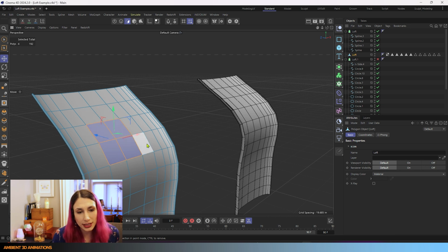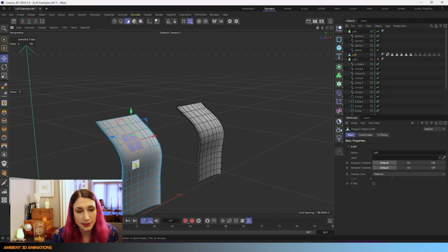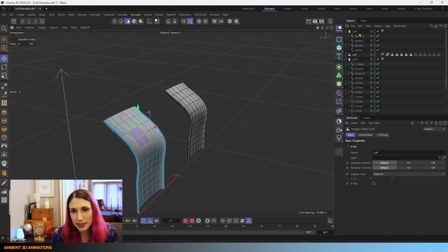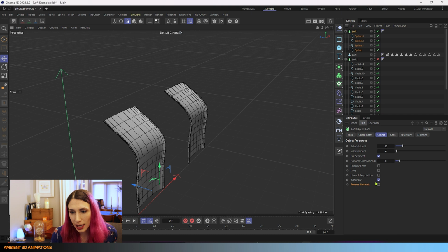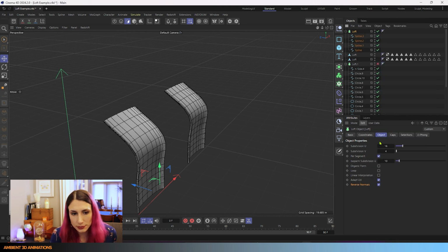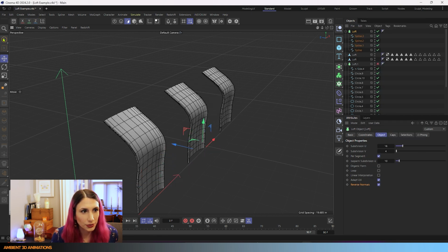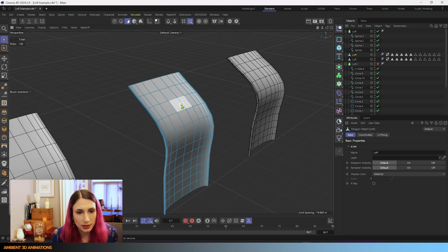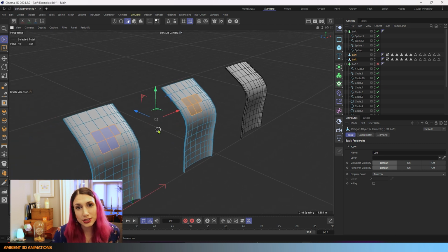What if while we were 3D modeling, we actually wanted this to be the reverse? We wanted this to be calculated as the outside of the object and this side to be calculated as the inside. Well, the way you would fix that is you could go back into your loft and you could choose reverse normals, and then we could create another copy of this and you'll see that it is swapped over here. So this is the new one, and you can see it's swapped from the old one if we click on these. So that's what reverse normals does.